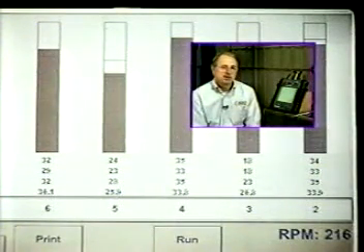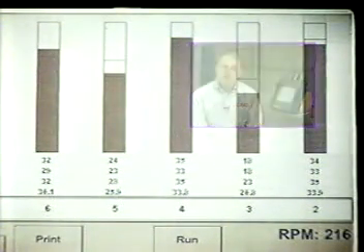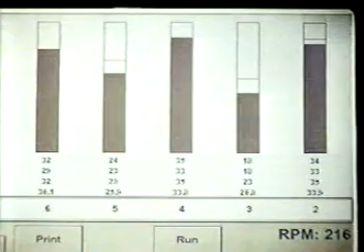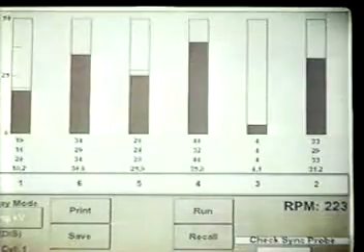At any rate, you can see we're between 22 and 30 kV. So it's a good test to check the electrical integrity of the coil pack, the electrical integrity of the secondary insulation, and of course the compression of the engine. Now what we're going to do in this vehicle, we're going to create a compression problem. And we're going to show you how easily this scope picks up during the cranking kV test the cylinder with the low compression. In this example of a cranking kV test, we've actually created a no compression problem on one cylinder.